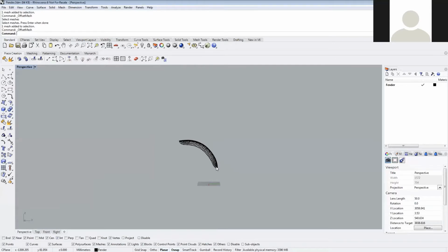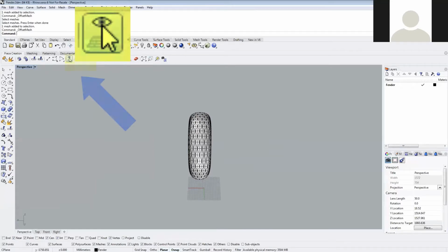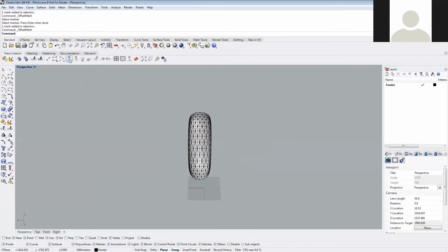So what we actually want to do is fit another construction plane. If we're looking at the side, we're going to try to get our plane so we're looking right at the edge, and it's just right along like that. The easiest way to do it is to use the camera as a bit of a guide. So we're going to rotate our camera and try to get it so we're looking right down at the piece where we want the construction plane to go. Then from the toolbar, we can click this icon right here, and this is going to create a new construction plane that's planar to our current view. When we click this, we can see our construction plane has now moved.